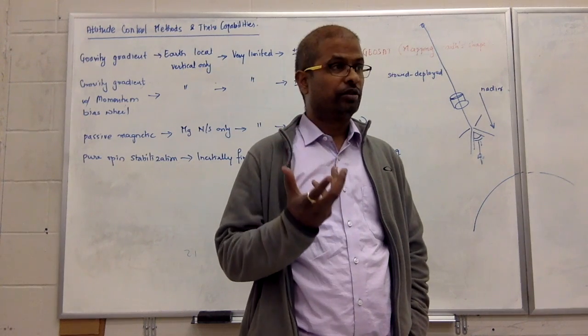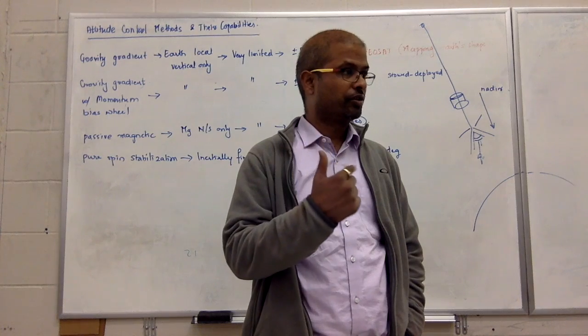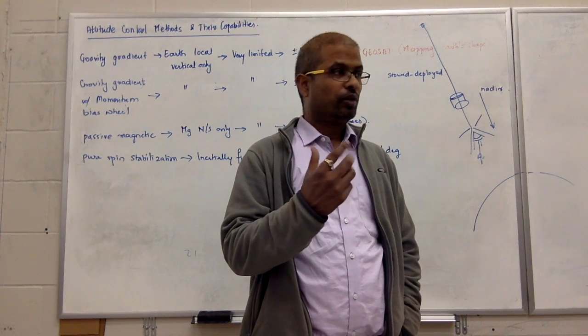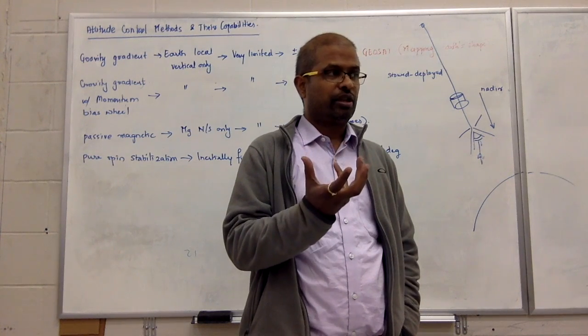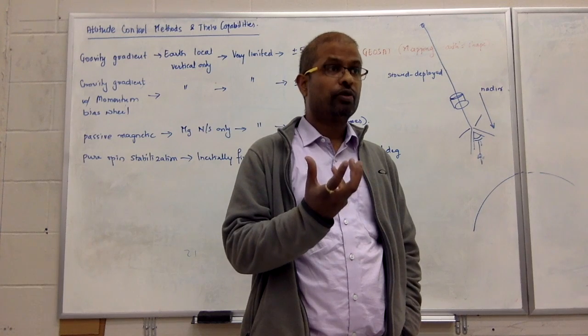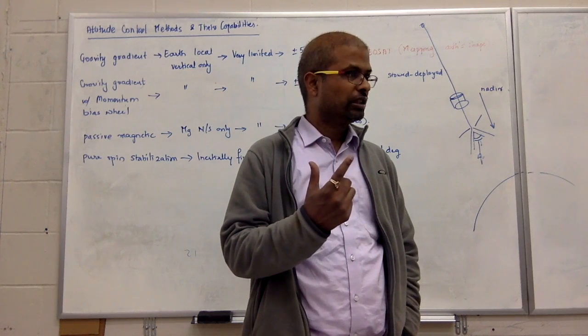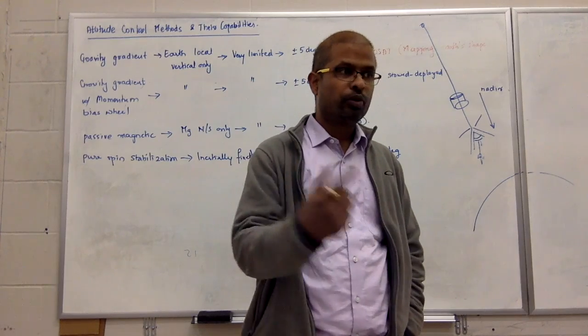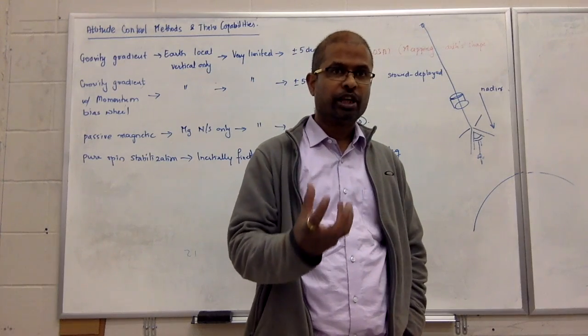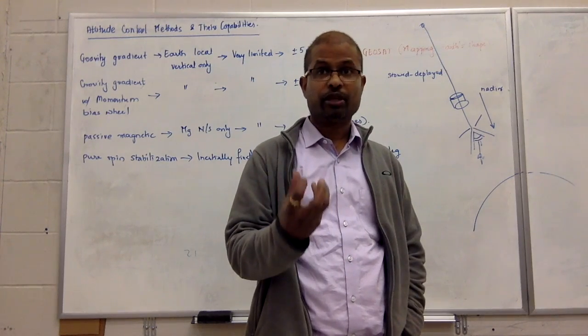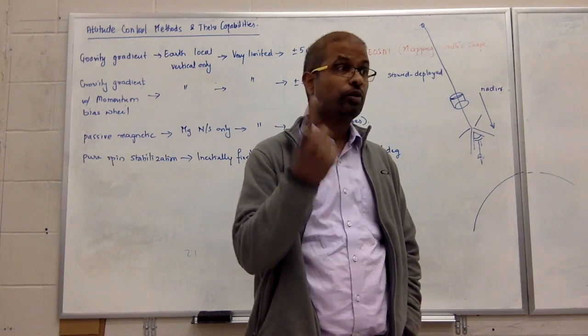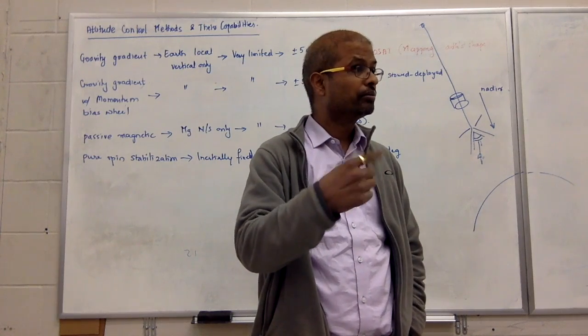What happens when you spin it? The satellite will start spinning in the other direction. Once the wheel stabilizes, the satellite will stabilize. Now, if you stop it, as the wheels slow down, the satellite will start moving. It will gain angular momentum. When the wheel stops, the satellite would have gained a lot of momentum.